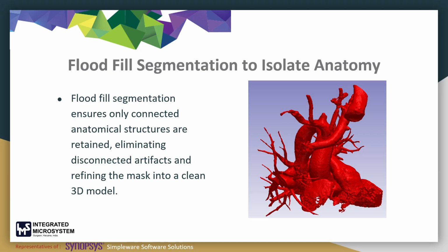Flood fill is especially effective in vascular applications where you need precise masks of tubular container structures. It ensures anatomical accuracy and minimizes the manual effort of cleaning the mask post threshold. The 3D rendering of the flood filled region helps validate the segmentation in real time. If necessary, the seed point can be repositioned and the algorithm rerun for better accuracy. This kind of feedback loop ensures that even novice users can confidently perform precise segmentation.